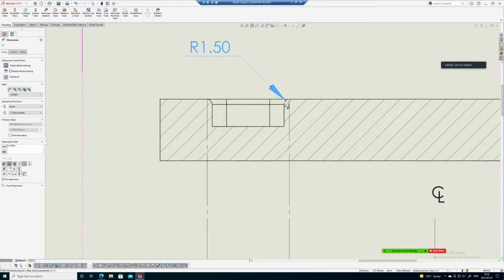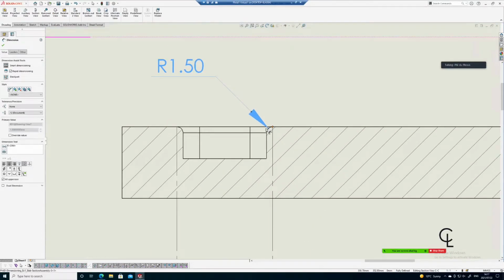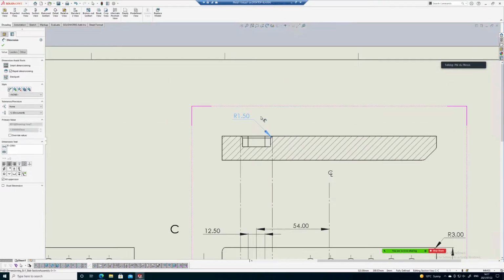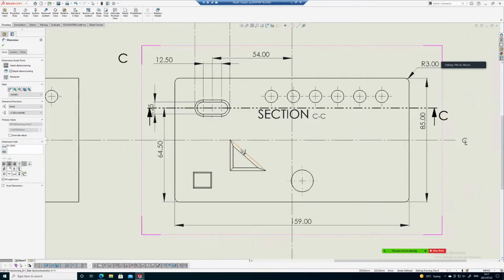Okay. Yes, Phil. Is there any way you could dimension that radius from the top view? Yes, except it contradicts a principle, in that you should only dimension in a view in which you can see the feature being dimensioned. True. Does that make sense? Yeah. So here I can see there's a curve. So let's just contrast that with this one here. That there is a chamfer. What's the difference between those lines and these lines here? Why isn't that a chamfer?